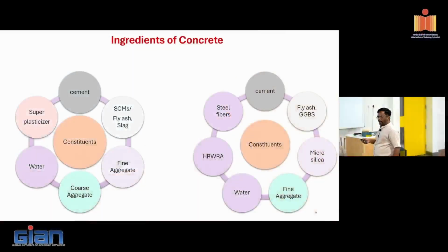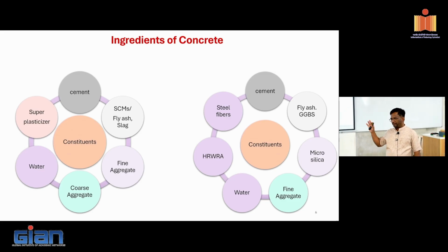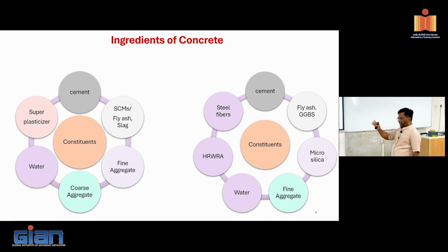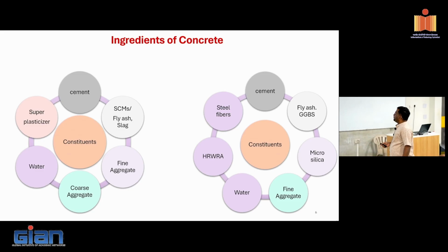So now again, why do we need to add fibers? Sir, it will reduce the shrinkage cracks. It will not allow the concrete to fail. So can we say it will give me crack resistance? Crack resistance, and it will help in reducing the size of the slab. Well, that depends upon so many factors. But as you said correctly, the steel fibers are added to give me the crack resistance. Depending upon how much I want, I can tailor the dosage of the steel fibers, right?